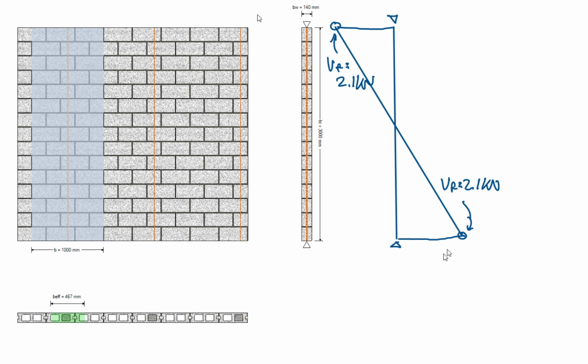Now between the two, since we have the same factored shear, I'm going to be a little bit more concerned about what we have up here, just because we have less axial load, which adds a little bit to our resistance, that PD term you might recognize in the formula. So in any case, what I really want to focus on is that we're looking at the very, very top of this wall, because that is where we have the highest shear. And you might be looking at this and thinking, you know what, I feel like that's pretty realistic to do, just because if I'm checking a wall for out-of-plane shear, I'm going to be most concerned about where it's the highest, right? And so that is actually what I wanted to get in on here.